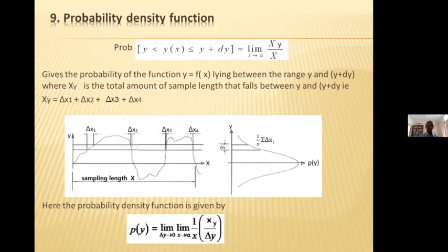In fact, roughness itself can be thought of as a signal, because when we measure the roughness, we take a piezoelectric crystal and move it over the surface and take the signal from it, and that is plotted as a roughness. And remember, this is only a line, a particular section of the surface. So this is also a signal analysis, and this is useful in our roughness characterization, also in signal analysis.